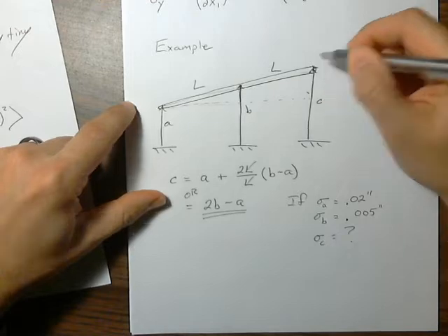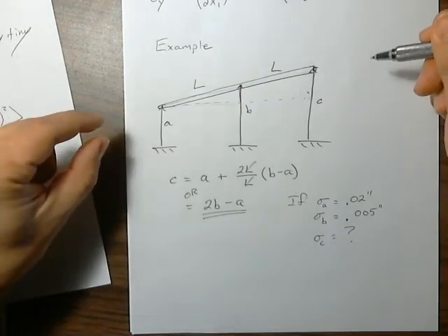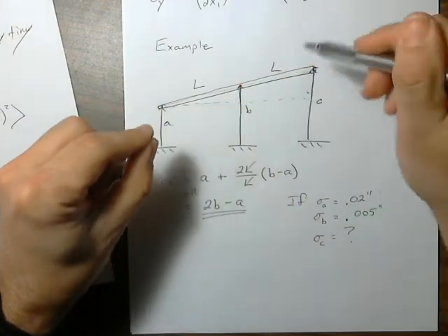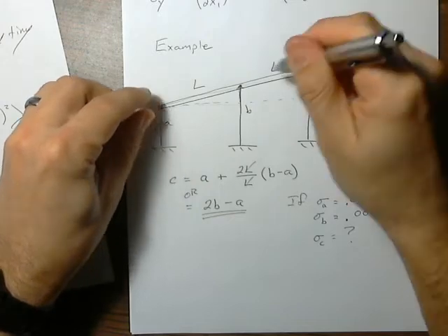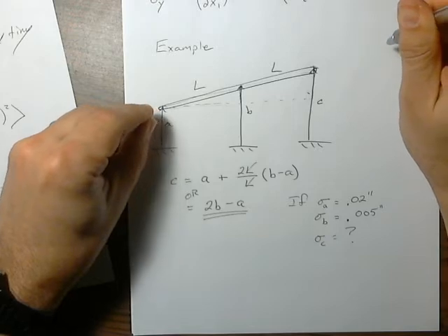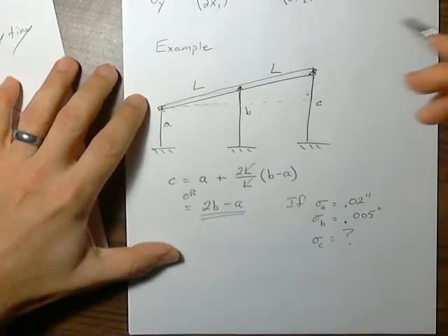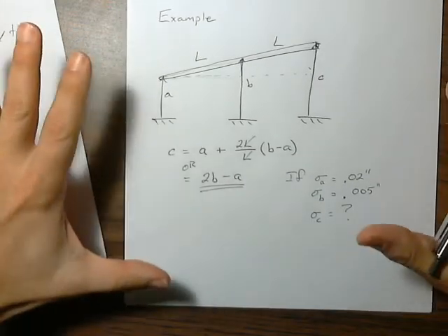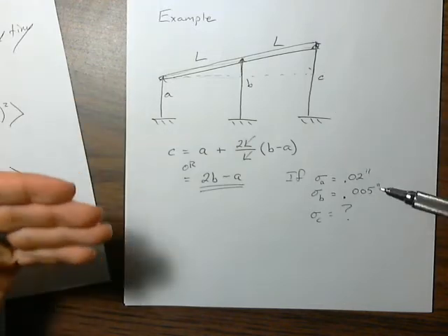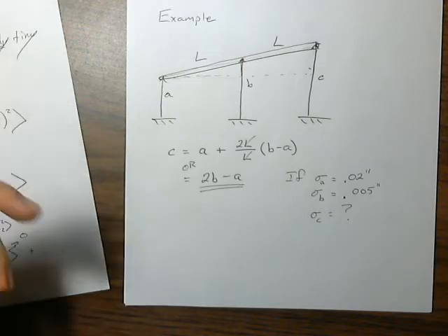Yes, you can locate this point anywhere you want. But all of a sudden, you notice that if you only have finite knowledge of the actuators you're using to locate a robotic arm, there are certain modes of operation where you're sloppy as all get out at the end of the robotic arm. And so we have to take that into account when you design the mechanism. When you see that these problems can come up, you've got to take them into account.